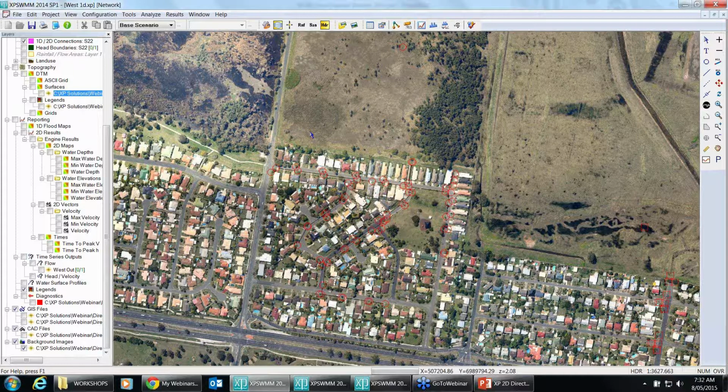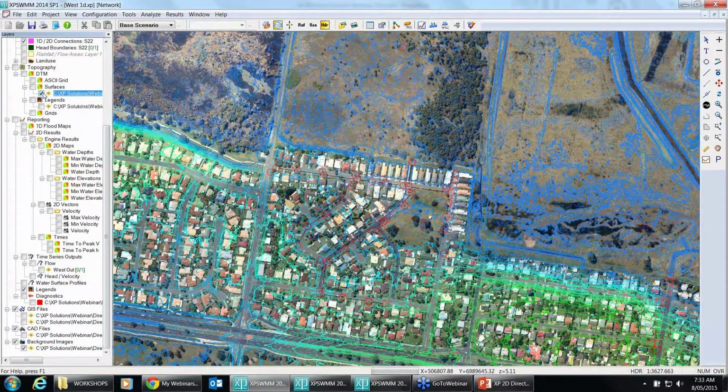In terms of data collection, in conjunction with some surface information, be that LiDAR or ALS or aerial survey formats, it's very quick to put a model like this together. Those electronic databases just make life a dream for modelers of stormwater. Very quickly we can build a model like this, and I'll turn that surface back on. That LiDAR surface had a 1 meter point resolution, and then we're throwing our 2D model over the top of this. We could be at this point within 10 to 15 minutes, almost no time at all. So very efficient. But of course, data is king.